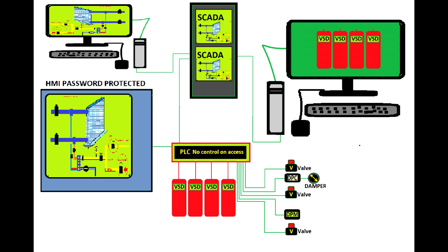There are things we have to consider when we design an air handling unit that supplies air into premises designed for production of pharmaceutical product. So we have to make sure that we're controlling the change rates, the pressure cascades, the temperature, and the relative humidity.